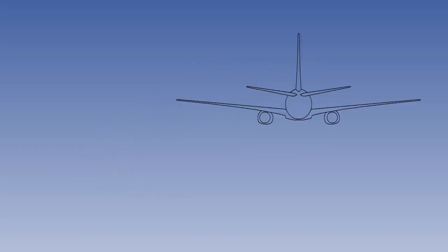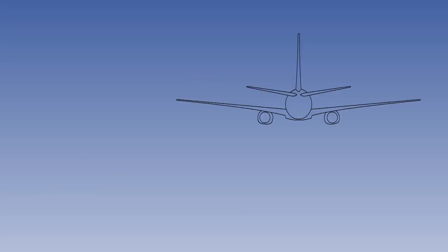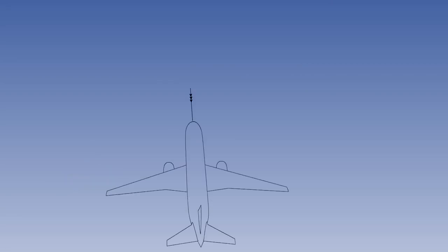If the side slip generates no rolling moments, the aircraft will neither roll further away from nor back towards wings level. This is neutral. If the side slip generates a favourable rolling moment, the aircraft will roll back towards wings level. This is stable due to side slip. The degree of lateral stability an aircraft has is the net result of the contribution of its component parts. First, we will look at the contribution of the wing.